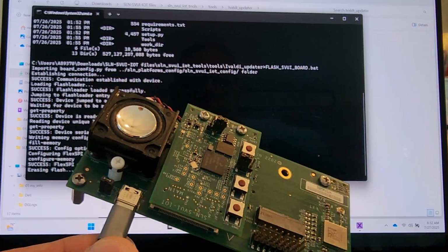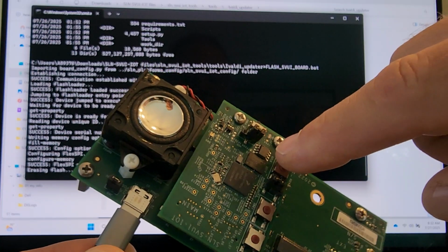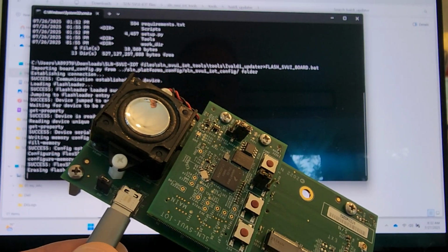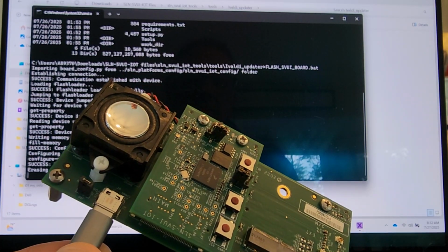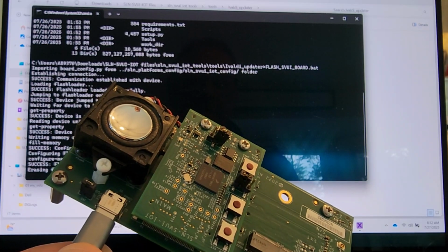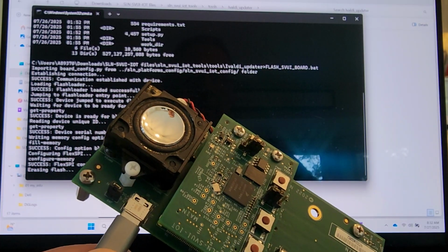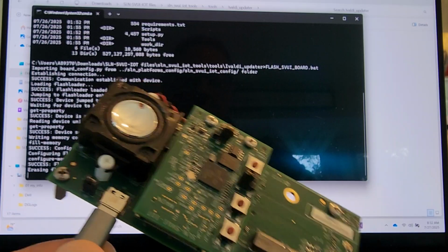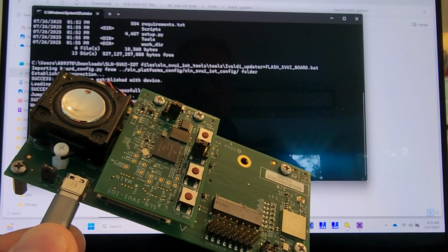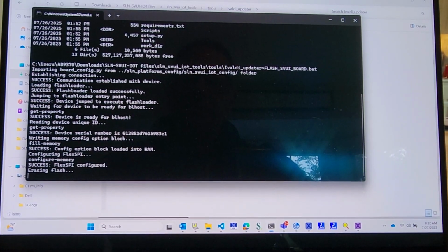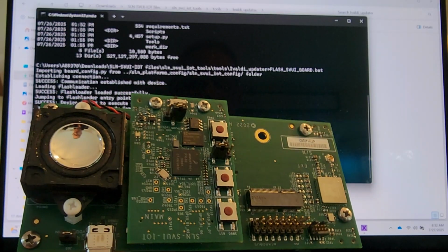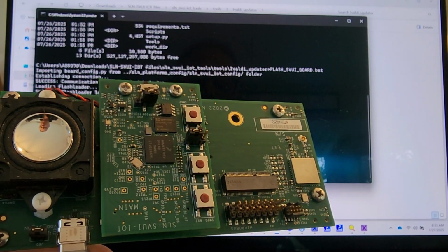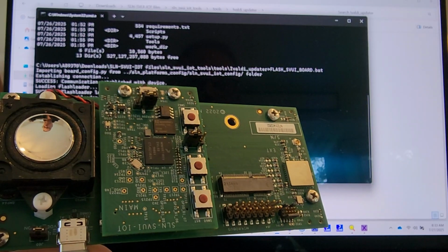this guy. So it's basically, here's the external SPI flash. I think that's 256 megabytes. External SPI flash. This particular I.MX RT does not have any internal flash in it, so we need to run this script. So it's going to continue to run, and it's loading up the freshest demo projects for us. So we'll let that continue on.